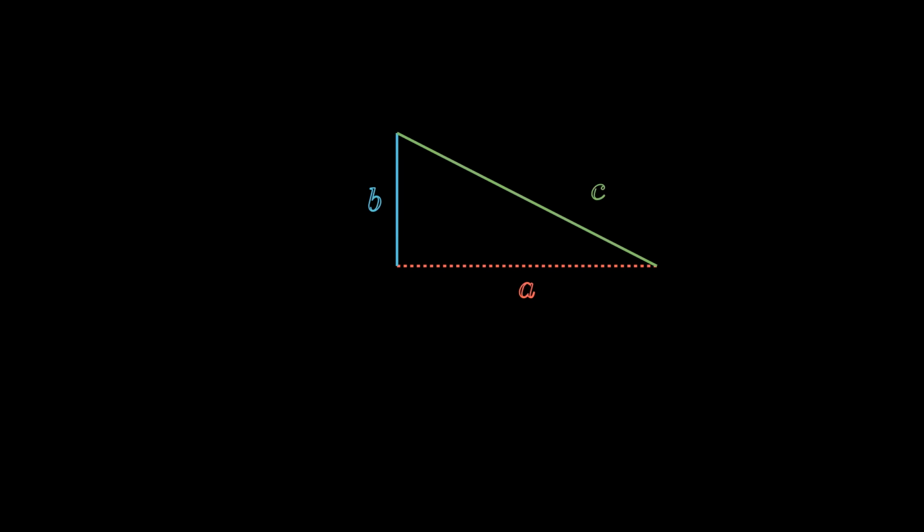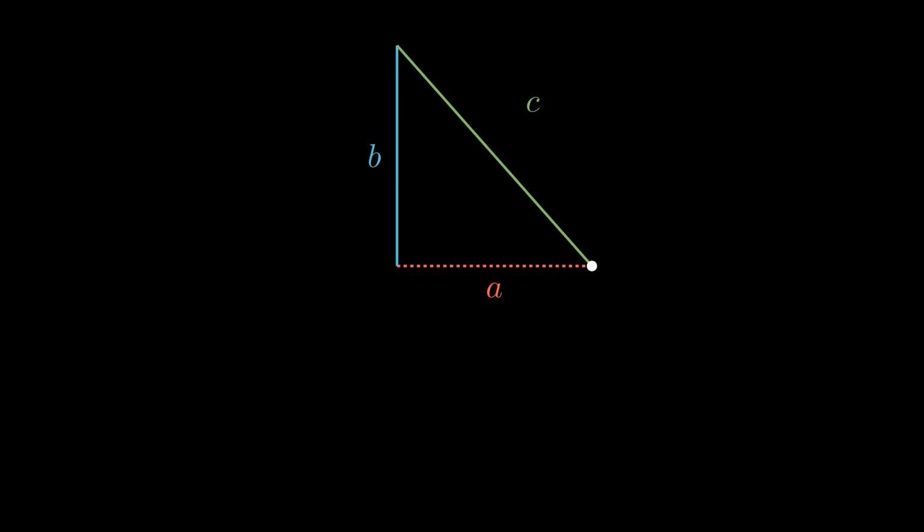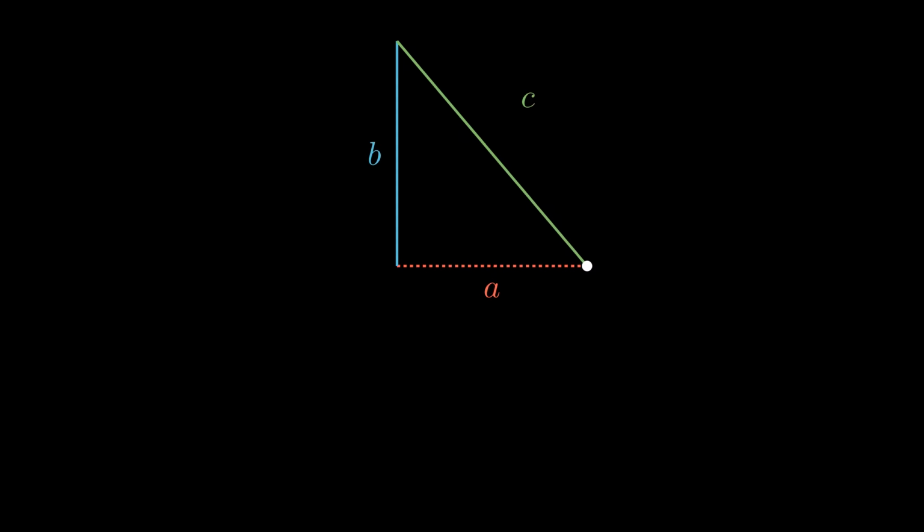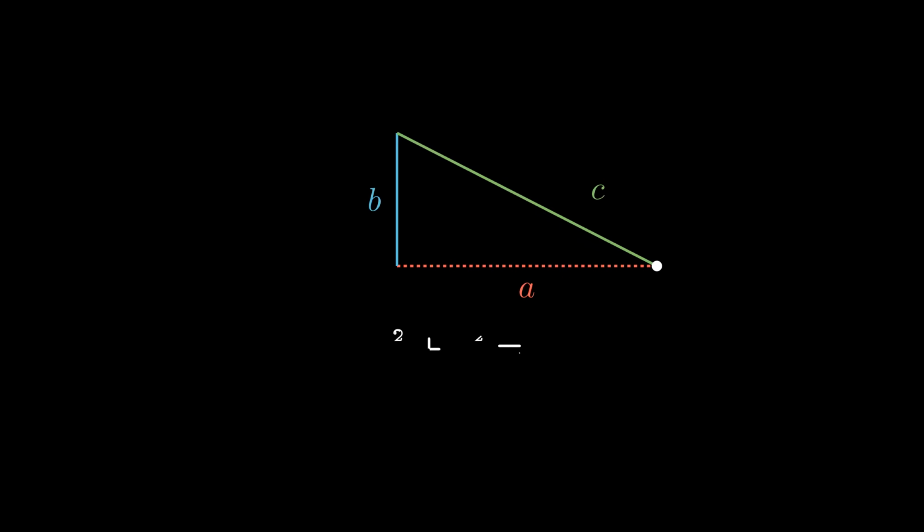Let's take a look at one of these arms, represented in this right triangle. Since the hypotenuse is fixed by the length of our physical arm, we can figure out the height of our rail carriage above the tool, and how far our arm will extend out in the direction of our tower. Since we will more often work with how far we want our arm to extend, we'll work with the bottom base and use the Pythagorean theorem to solve for the missing height.